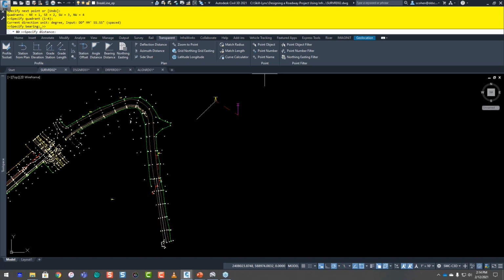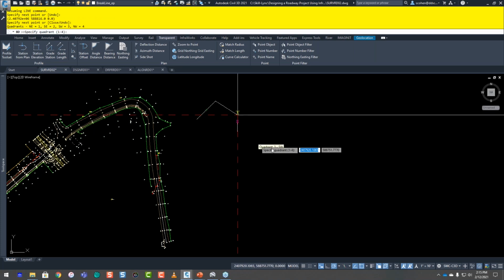Okay, for instance, the chamfer command, or the fillet command, where it would be the radius. Whatever it is, you're prompted for a distance, or the offset tool, you could type that in, or you could just say match the length. So I could click on match length here. Again, it says select entity to match length. I'll go ahead and click on this. And now it grabbed that there.